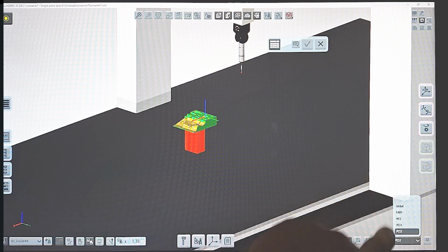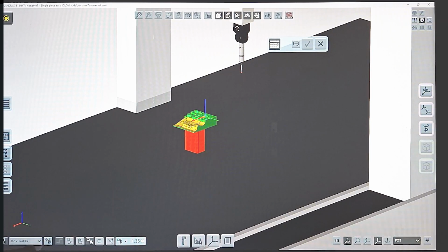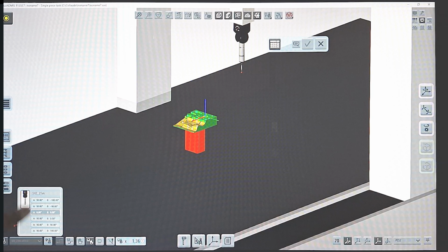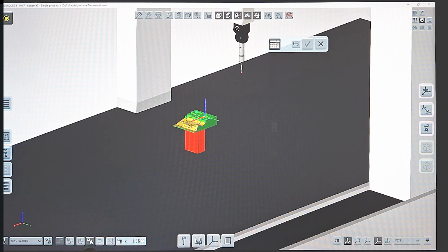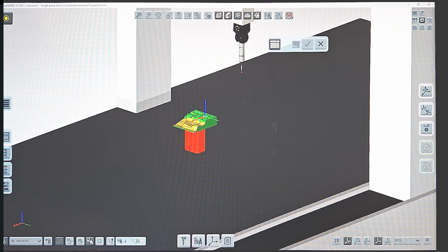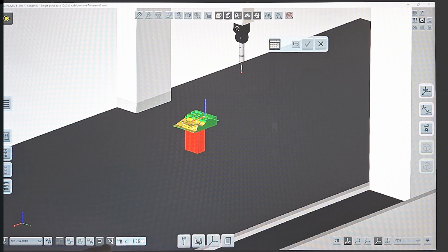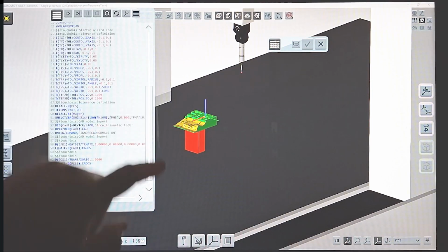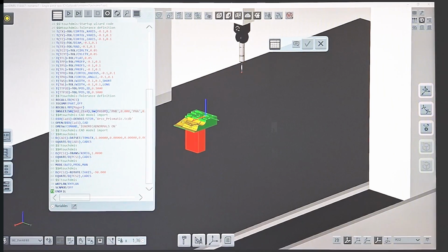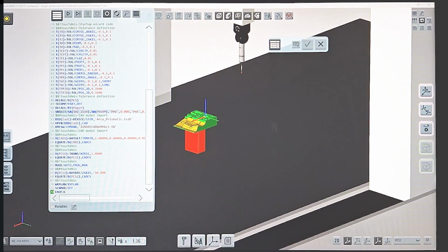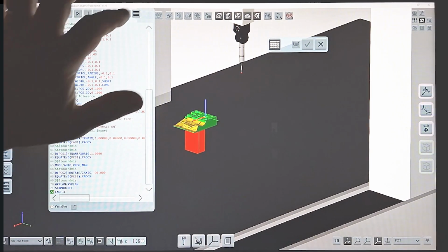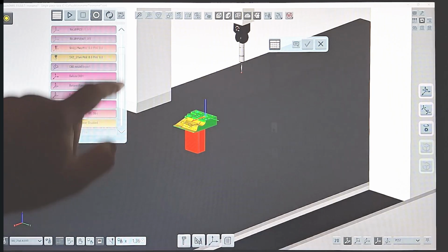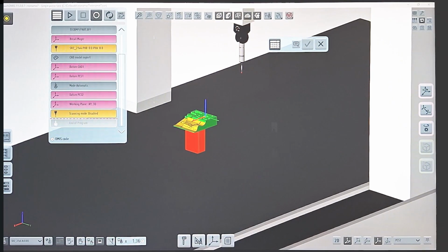With a simple tap, we can change the reference system, we can select tools, we can change mode: manual mode, prog mode, or the CNC mode, scan mode on or scan mode off. We have a part that shows the DMIS code. But for everyone who is not keen to use a DMIS code, we can easily switch into the block view, in which we see step-by-step executions and don't see the code anymore.